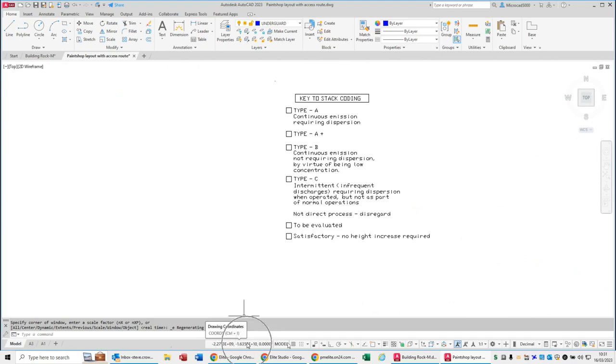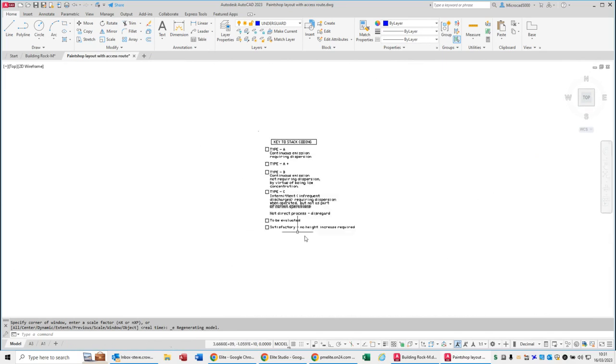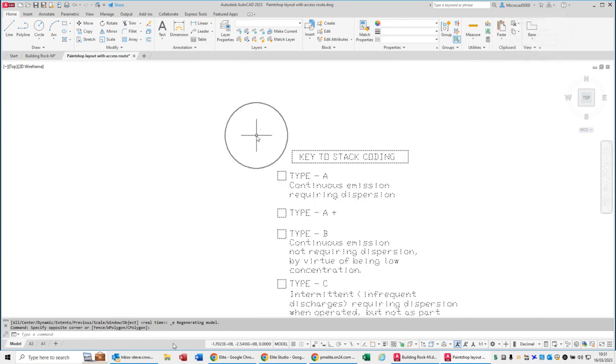And this drawing was sent to me because of an issue with it. When I measured one of these letters here, how high is that letter E there, for example? It is 250 kilometers high. That's quite a big bit of text, isn't it? So somebody's obviously accidentally put that text in at a massive, massive scale. So what the guys were doing was putting a window around it to delete it. The trouble is, you can see that one pixel just there, that is the drawing.